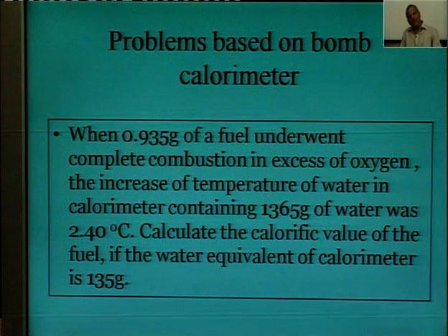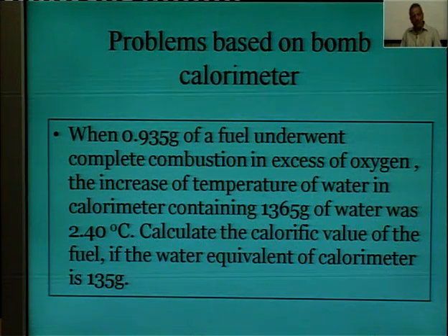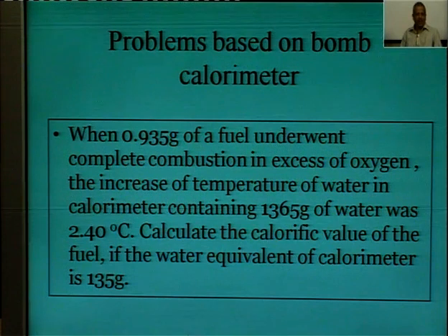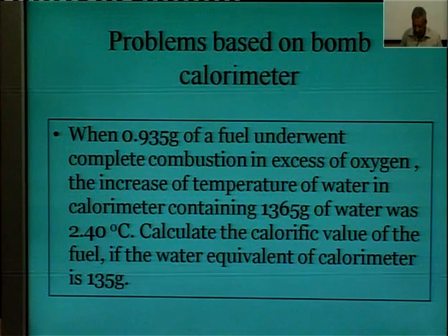If we want to know the calorific value of the fuel, the substance is 0.93 gram and the calorific value we want to know is Q. The water is 1365 gram and the water equivalent of the bomb calorimeter is 135 gram.